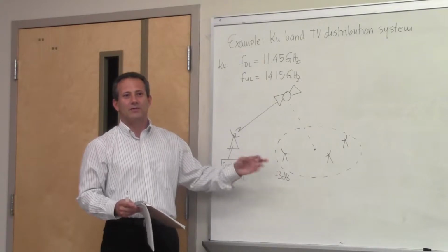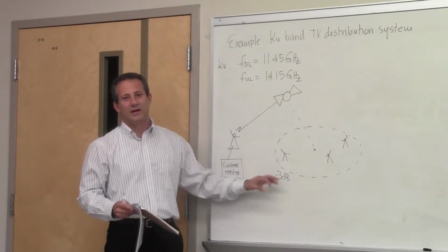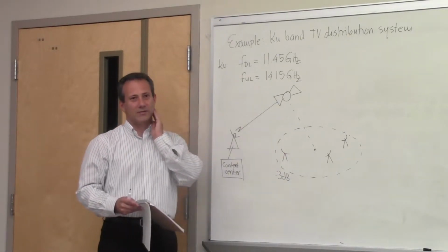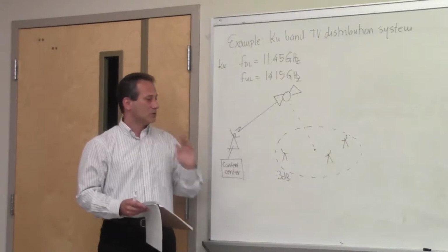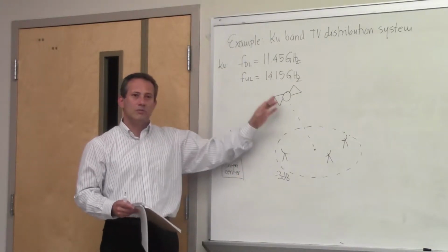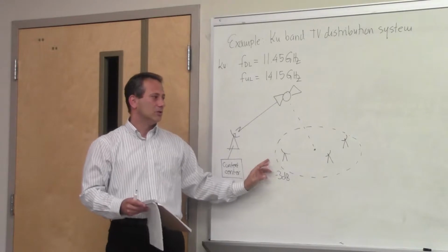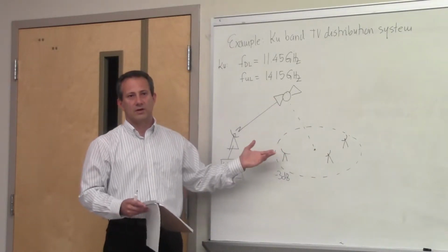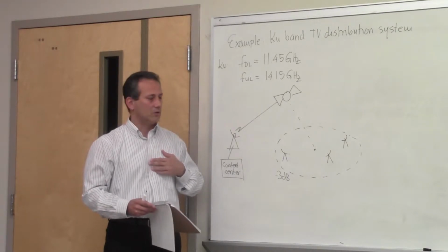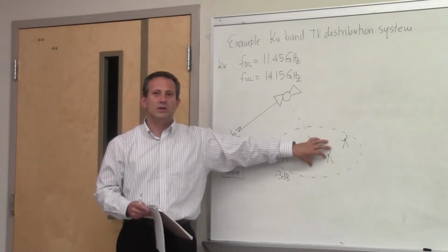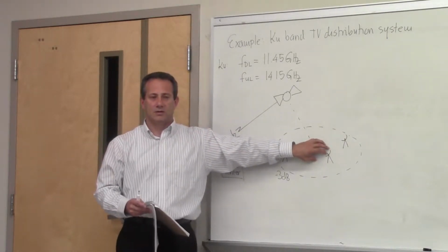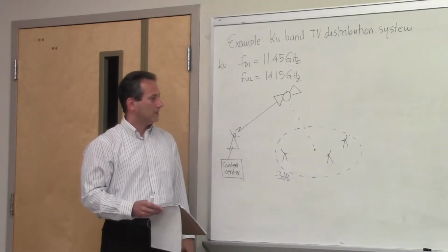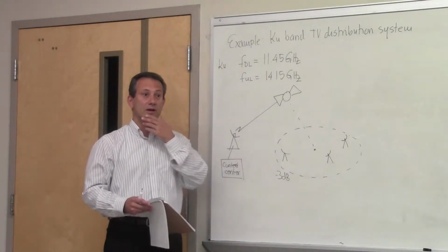You cannot say whatever is the minus 10 dB contour, because then the guys on the outskirts are going to have very poor coverage, right? And usually when you do your link budget, you dimension it so that the users on the outskirts of the coverage area have the reliability that you require. If you happen to be within a main beam, then you have a slightly better reliability.